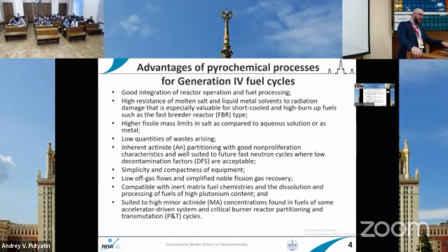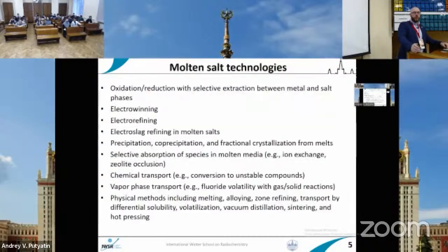So with a short period of storage of spent nuclear fuel, very high concentrations can be reached. There is no danger of the formation of precipitates because there are no countercurrent flows between the equipment, so there is no danger of the formation of precipitates like we discussed for the Purex process or other processes. So there are a lot of advantages of these processes.